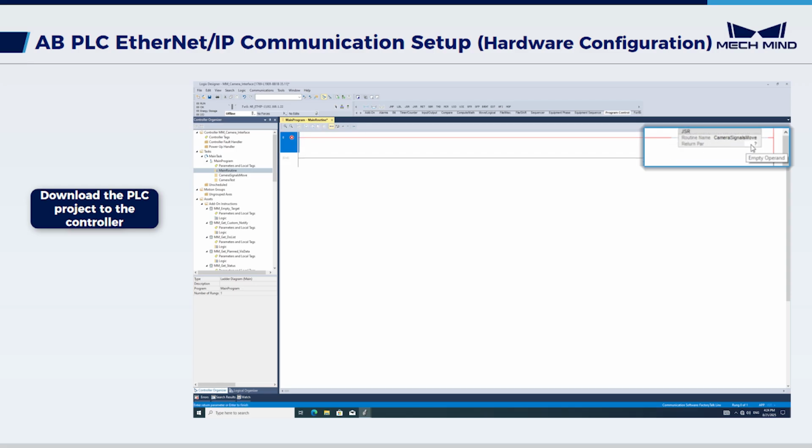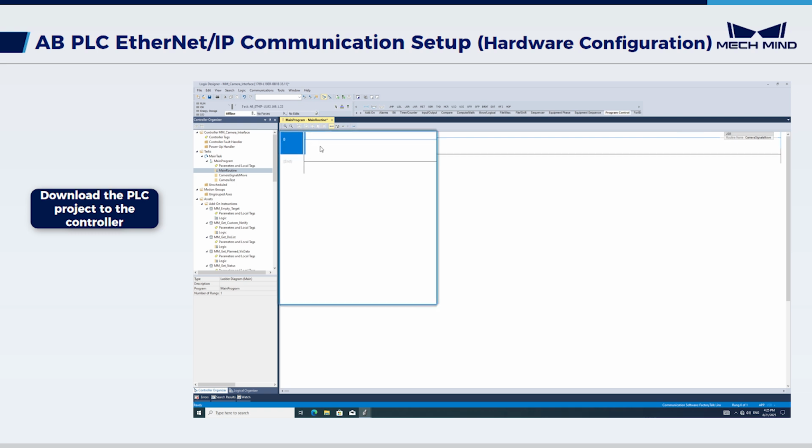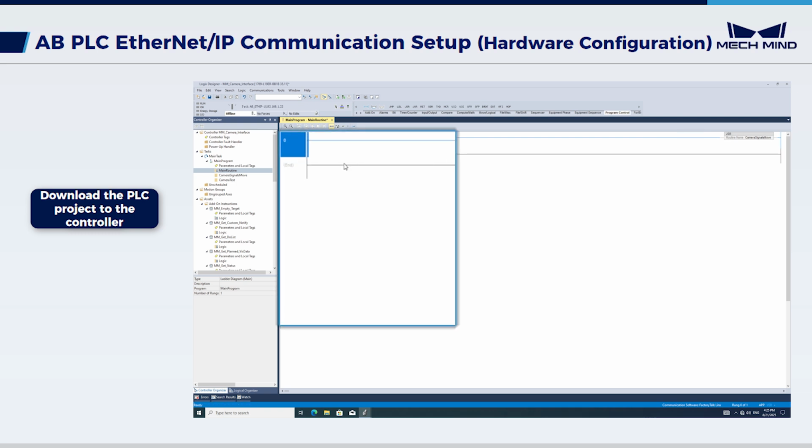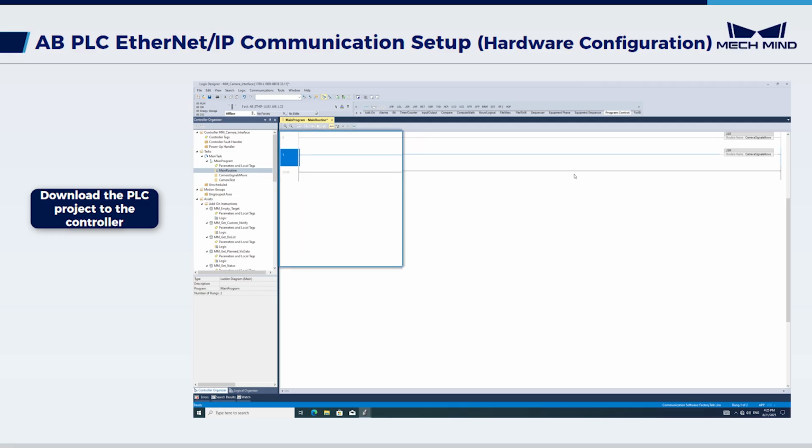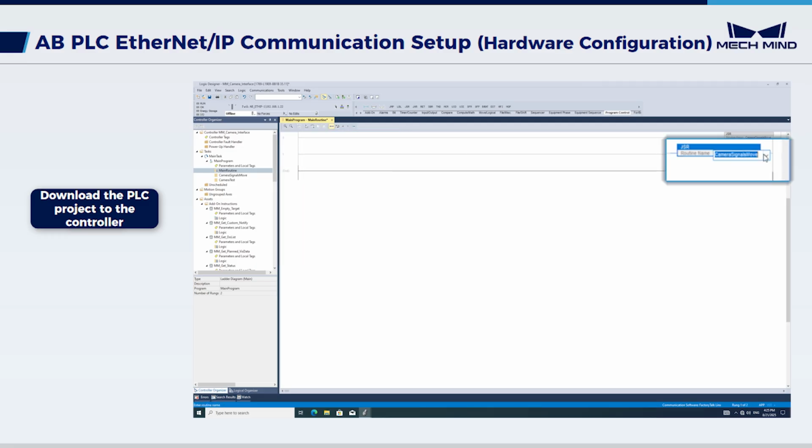Studio 5000 will hide empty parameter slots, which is a quick way to tidy the rung, but don't clear parameters that the routine requires. Copy and paste the rung containing the first JSR to create rung 1, and edit the pasted JSR target to camera test. Then, use download to transfer the offline project to the target controller.